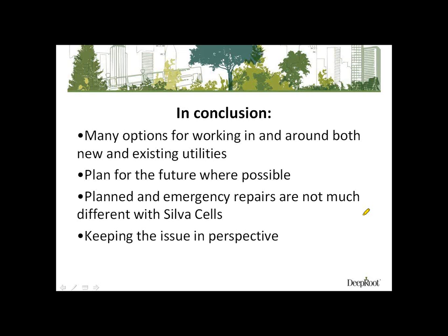Should Silva Cells be used to interconnect several trees in a row? In other words, just to spread the whole system in between two tree openings down, let's say, the length of the street? Yes. Anytime that you give trees an opportunity to share soil volume, you can do with a little bit less soil volume per tree, because those trees are able to share. Also, it works great to use Silva Cells just as a breakout device.